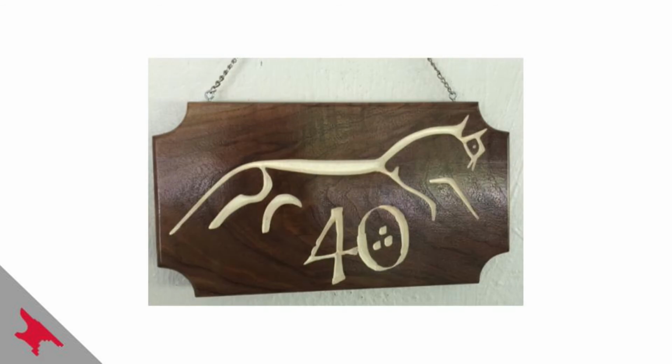Here is a sign made using the same vector image of a horse from earlier. The order of operations was to first create the image in Inkscape, import it into VCarve, create toolpaths in VCarve, then cut the project out on the big red CNC machine. I've also engraved this on glass using the laser cutter and cut it out of heat treat vinyl and applied it to a t-shirt, all using the same original vector drawing.